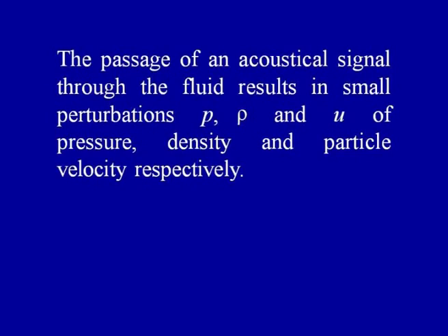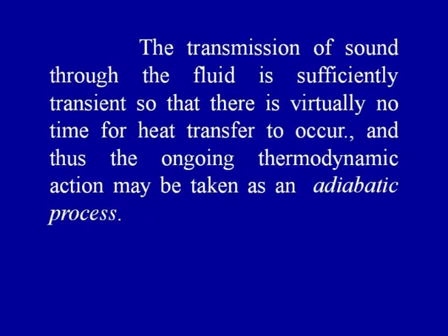The passage of an acoustical signal through the fluid results in small perturbations, small changes in the value of the pressure, in the density and in the particle velocity over the undisturbed values. The transmission of sound through the fluid is sufficiently transient, so that there is virtually no time for heat transfer to occur.